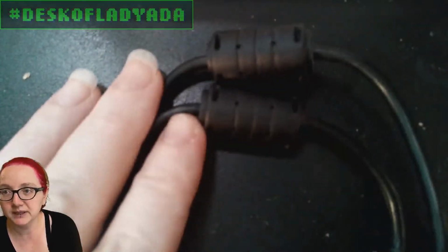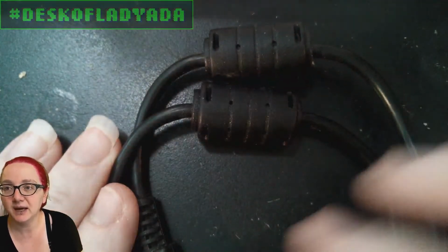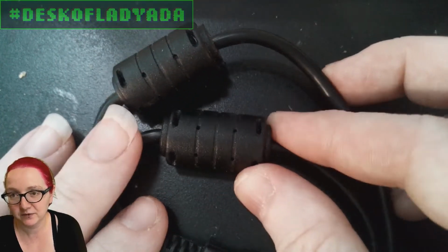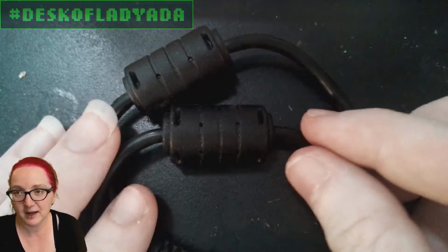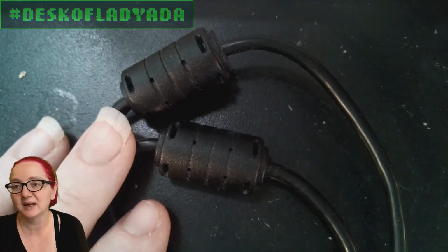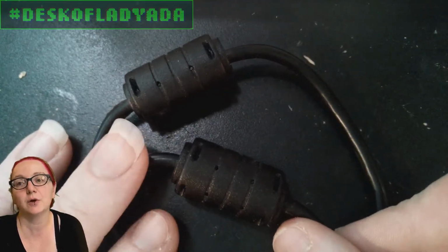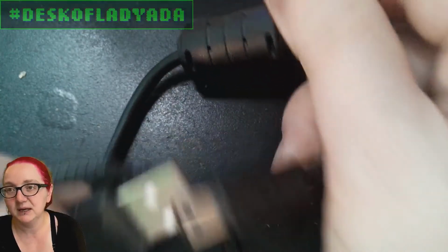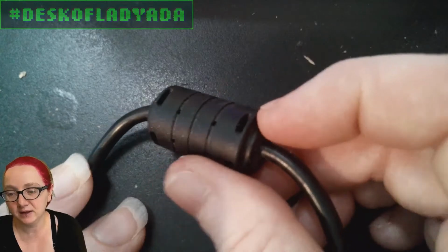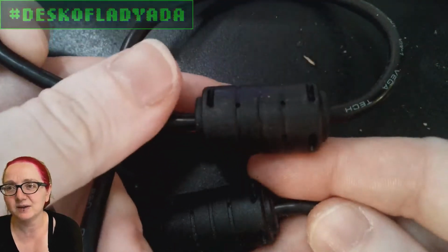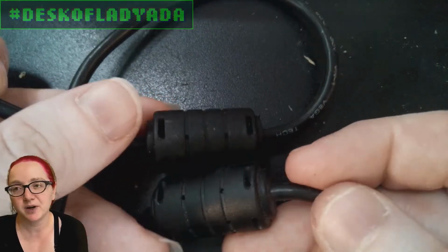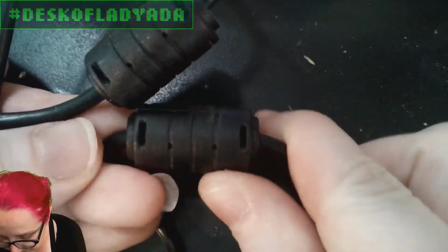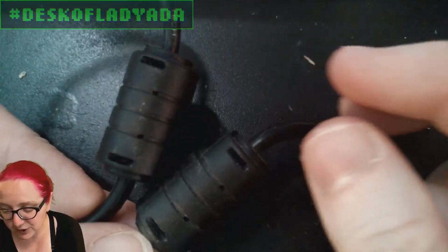So this is what you normally see. This is a USB cable. Although you don't see it as much anymore, and I don't know why, maybe USB hosts or USB devices are better at reducing EMI in different ways. Maybe they have inline resistors or lower drive strength. But this cable, USB to mini, has a ferrite bead installed on both ends, which is pretty serious. Maybe it was required for the product that this shipped with, who knows. But these are molded in, and if you can get molded in, great.